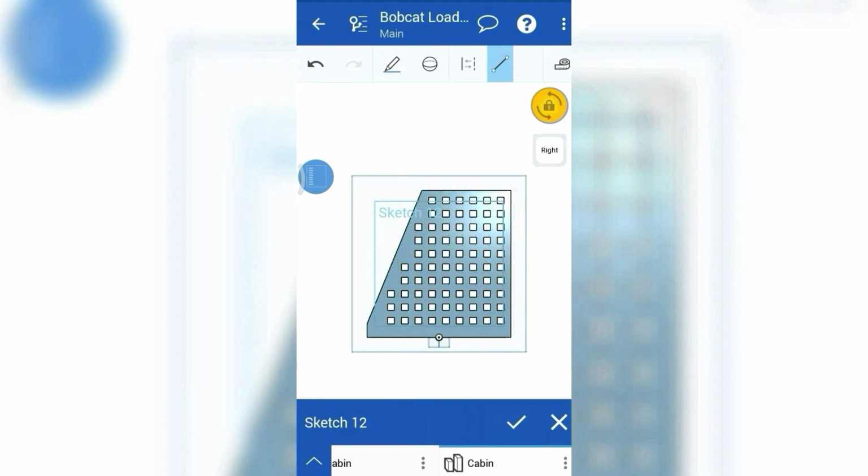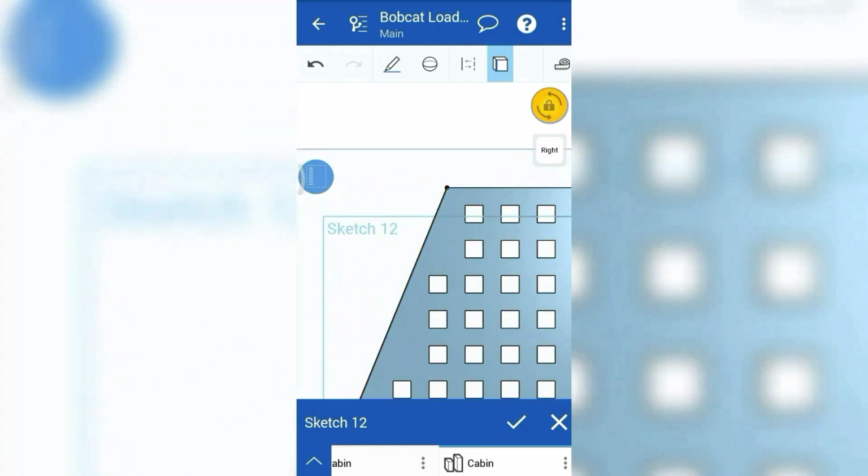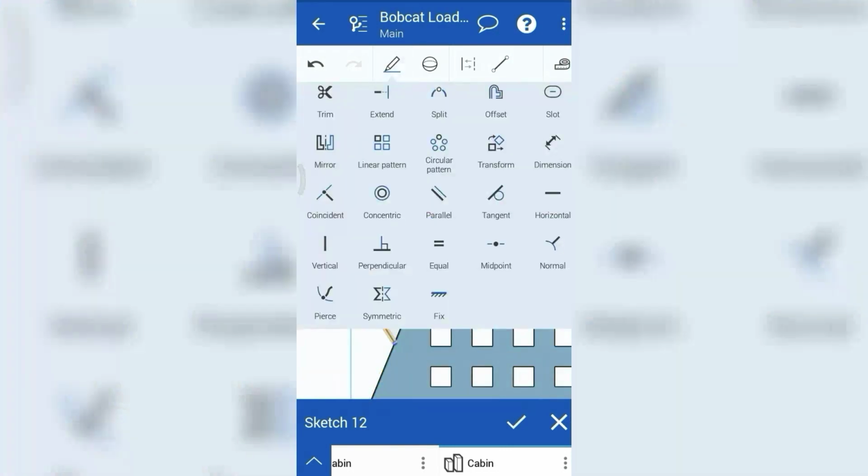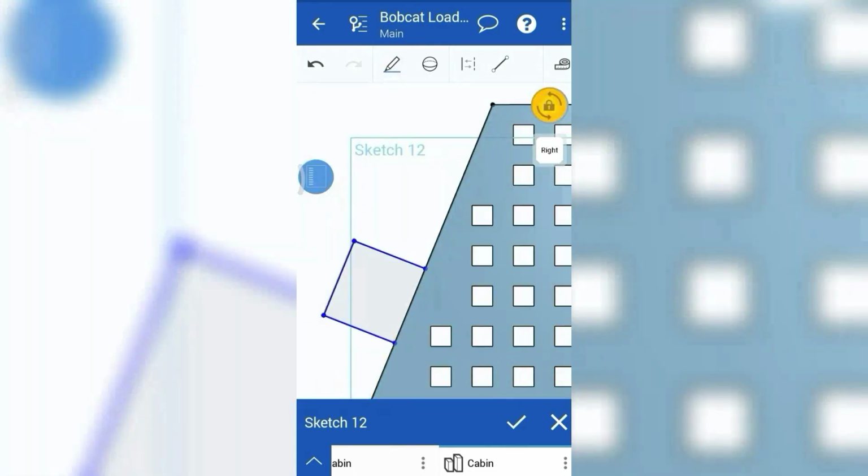In this sketch, I will require one edge of the face which can be drawn by means of use command. We will create a rectangle by using lines. The length and the width of this rectangle are 230 mm and 60 mm respectively.